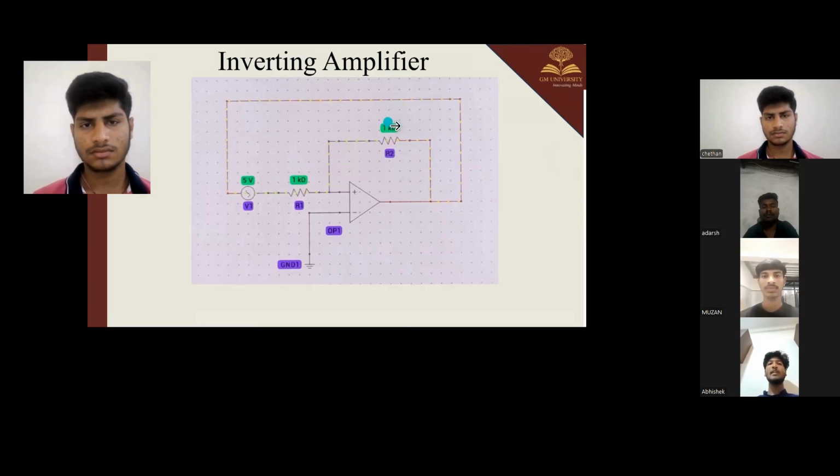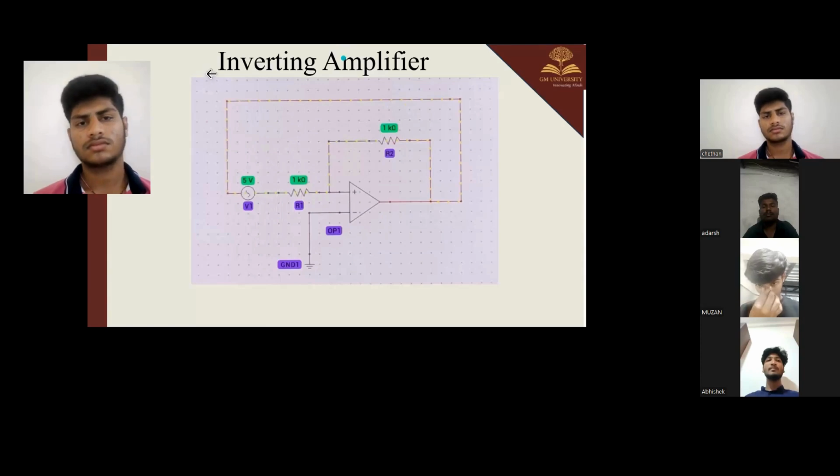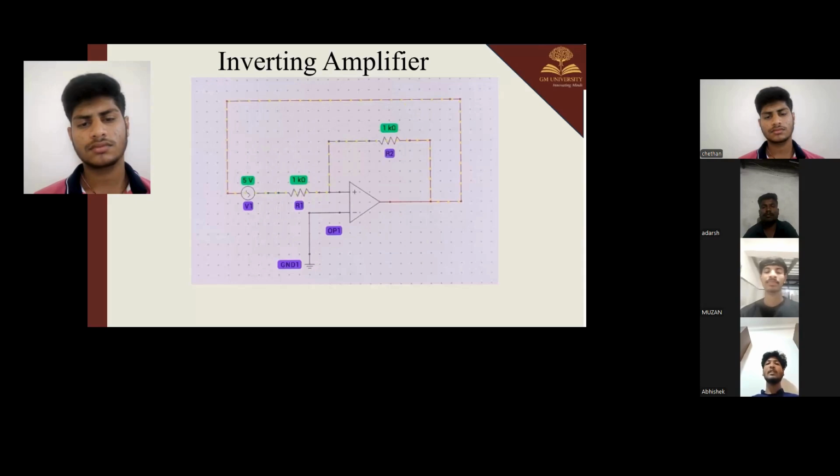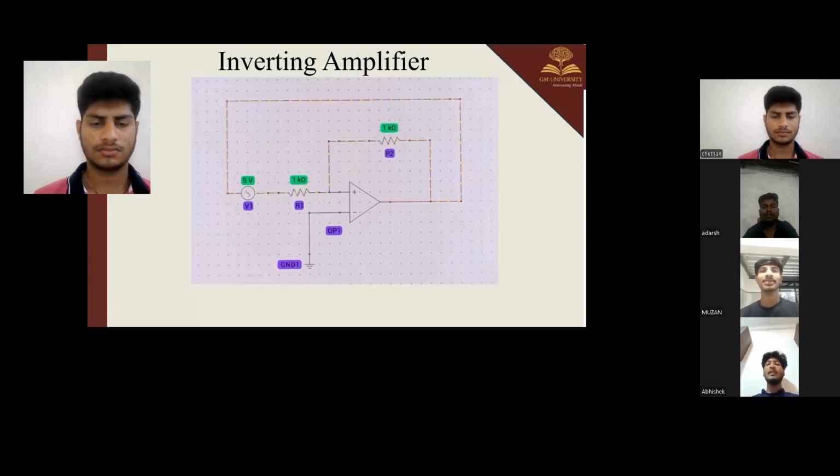To understand the inverting amplifier, imagine that the operational amplifier has two important rules. First, the input terminals draw almost zero current because the op-amp has very high input impedance. Second, the op-amp will try to keep the voltage difference between the two inputs equal to zero as long as it is operating in the linear region. In the inverting amplifier, the non-inverting terminal is connected to ground, and the op-amp keeps the inverting terminal at the same voltage, which is also known as virtual ground. Because of this, the current entering through the input resistor passes through the feedback resistor, and this relationship creates the voltage gain.